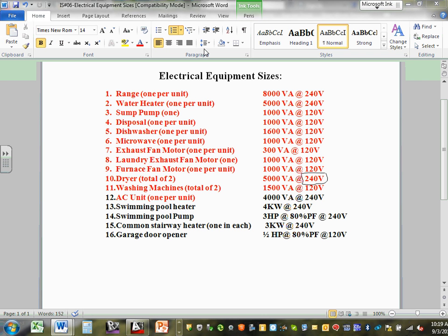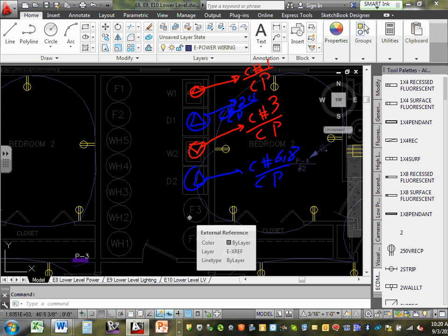So Derek, my friend, if you look at the water heater, what voltage are we dealing with? 240. Typically, guys, for the water heaters and the dryers, they're 30 amps. They're a 30 amp circuit, 30 amps dedicated. So for the water heaters, starting with the water heater right in here, you use this symbol as a disconnect. We need to provide a disconnect by code for them. Each one of them is going to have a disconnect.